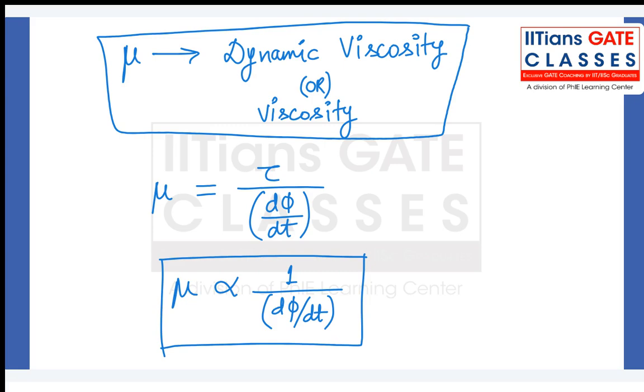And the thing which we call flow, if I say something is flowing, this means that quantity is showing shear strain rate, correct? So if I have a solid block, let us say a steel block, and I have the same cubical fluid element, let us say a water element, that block will show some certain value of shear strain when applying a certain value of shear stress. If I go to the fluid, that will show me shear strain rate. Continuously, its shape will keep on changing, and that phenomenon we term as flow.